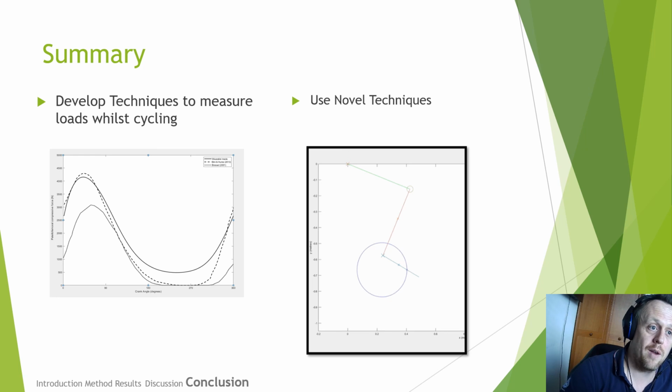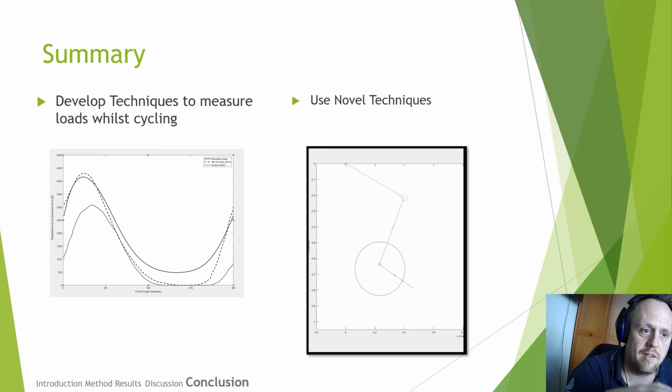So, in summary, we managed to estimate the forces in the knee using recorded reaction force data from the pedal. Rather than use traditional image processing techniques to provide the kinematic data, we instead used a simulated 2D model in MATLAB. We then used the generated data to complete the inverse dynamics to estimate the force in the knee.